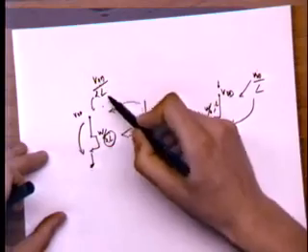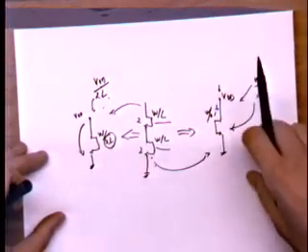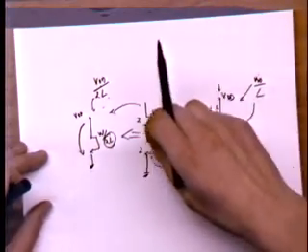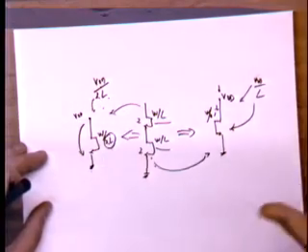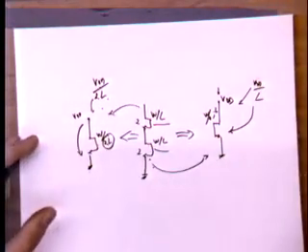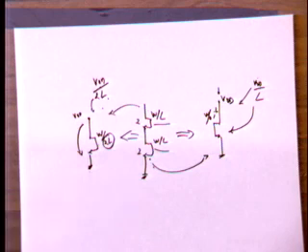And because this guy to the left has more current than the guy to the right, the optimal scaling will not be 2 in reality, but will be something more between 1.5 and 1.7, let's say. Okay? And if you look at real standard cells, that's what is done typically. But we'll go back to this in the homeworks in the future. So we'll have a chance to look at this from a simulation standpoint and look at what's the difference really between these two devices. All right?